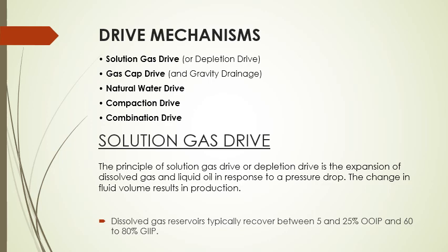or the presence of water below the oil can drive the hydrocarbon fluids out. And there is a combination drive. A combination drive mechanism can be a combination between water and oil, or water and gas. So I will start with solution gas drive. The principle of solution gas drive, or depletion drive, is the expansion of dissolved gas and liquid in response to a pressure drop. The change in fluid volume results in production. Dissolved gas reservoirs typically recover between 5 and 25% of oil in place, and 60 to 80% of gas in place.